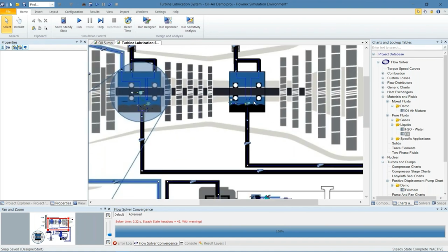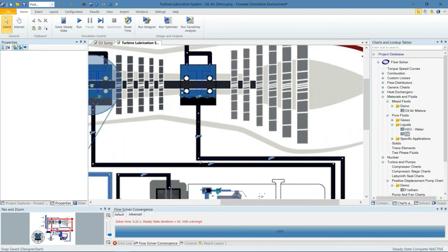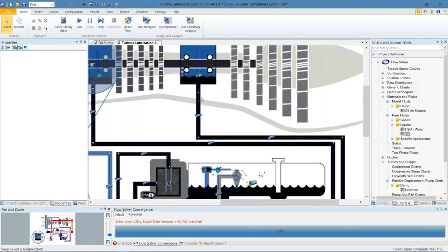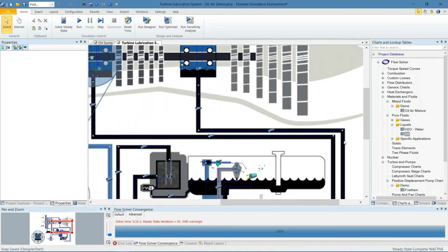This then flows through the series of pipes. All the way along, we apply elevations to the nodes to correctly account for the elevation pressure drops. The Beggs and Brill correlation, as I mentioned earlier, accounts for inclination differences in the pipeline and is one of the only correlations that is suited for all inclinations. You will find some two-phase correlations that are ideal for horizontal flow, other ones that are ideal for vertical flow. The Beggs and Brill correlation is suited for all inclinations, so it makes it an ideal correlation for this particular application. So here we specify our elevations of the nodes along the way,